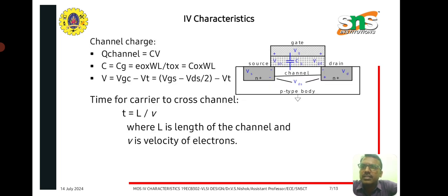So the equations are given here in this slide. Q channel is equal to C into V. So the respective equations are given here. The charge is calculated with the help of capacitance and the voltages like VGS and VDS and threshold voltage VT. Similarly, the transit time, that is the time for a carrier to cross the channel, is given as T, which is equal to L by V. L is the length of the channel and V represents the velocity of the electrons.